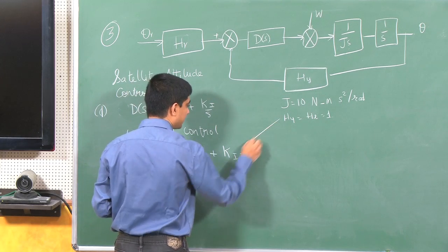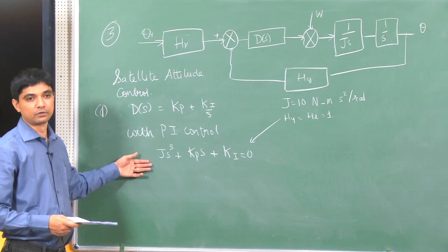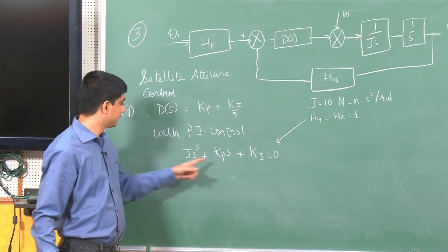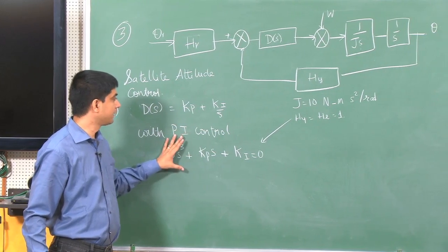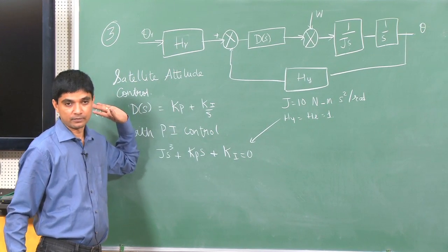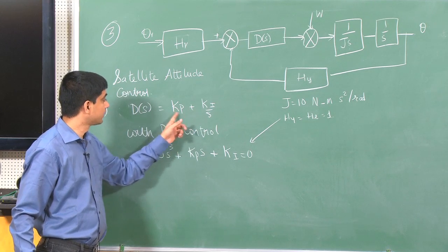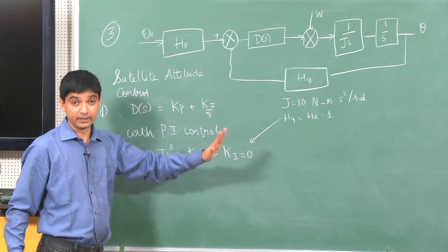This is again assuming this to be true. Now this is unstable. I don't really need to analyze this any further. So with the PI controller I know it is unstable. Now it doesn't really help me to compute the steady state error anymore, because whatever I do, the system is unstable. Therefore, just doing a PI control and then doing the steady state analysis is really meaningless.